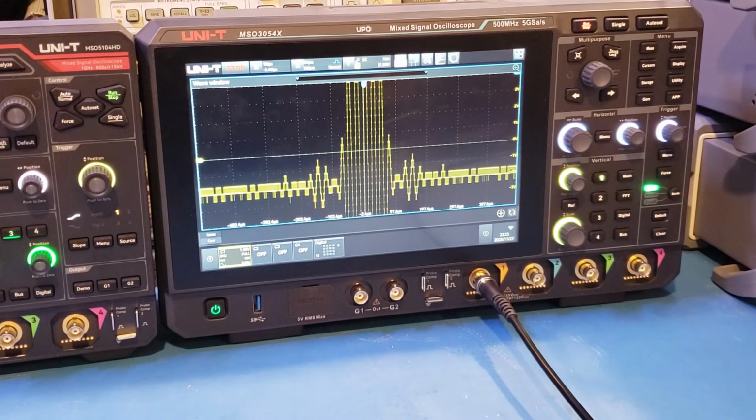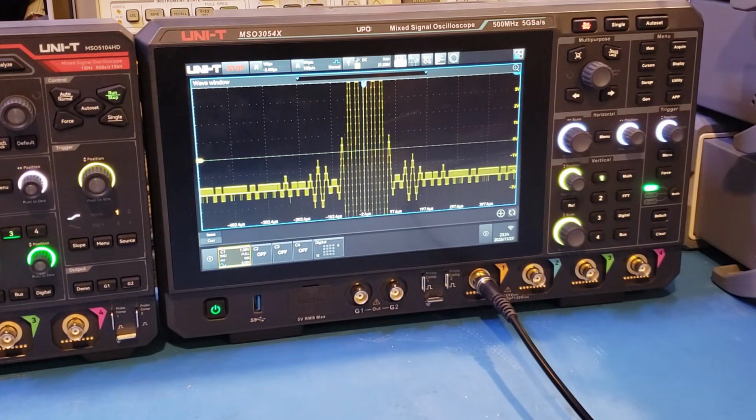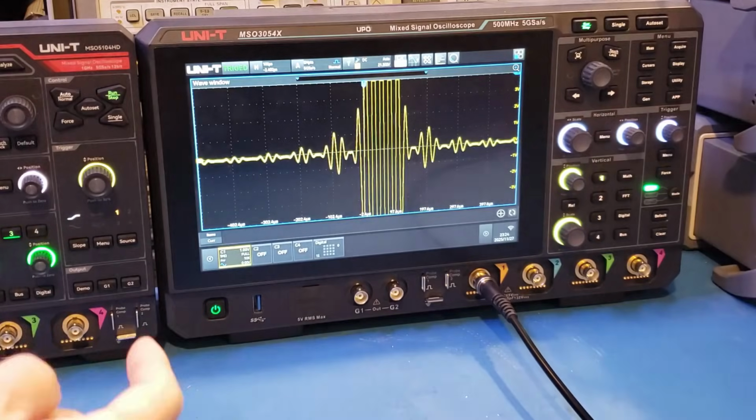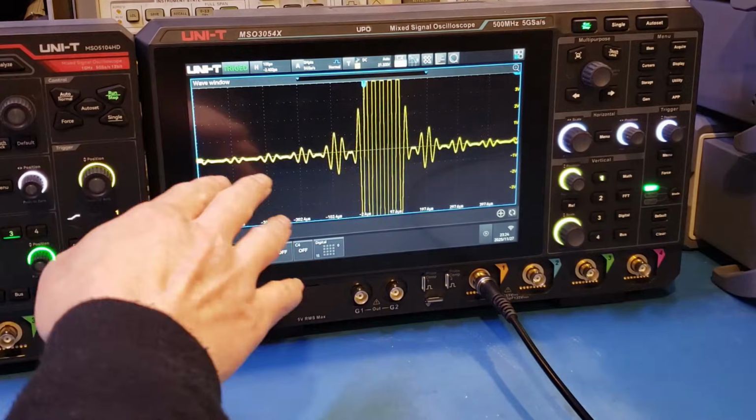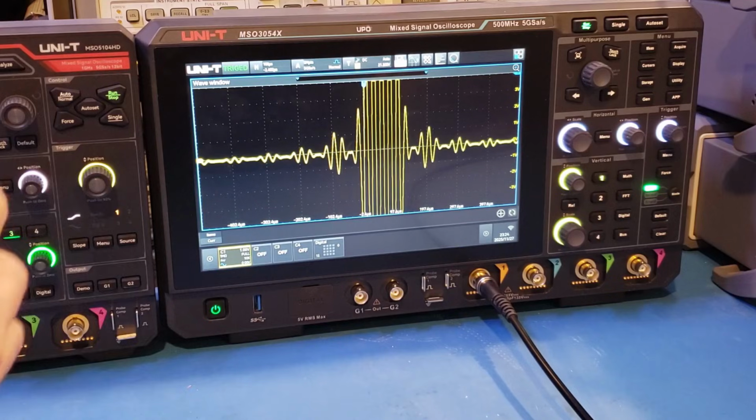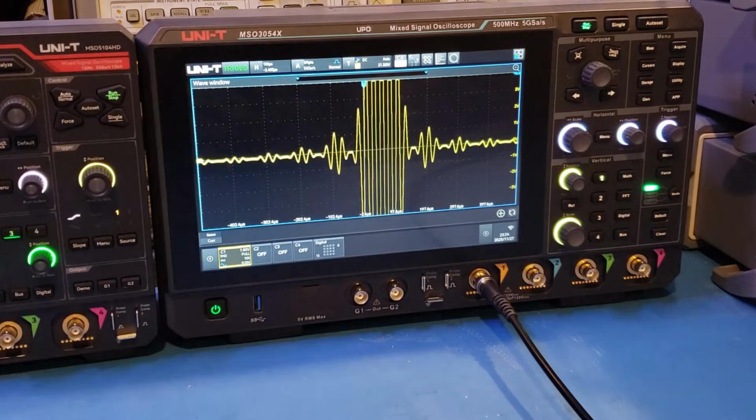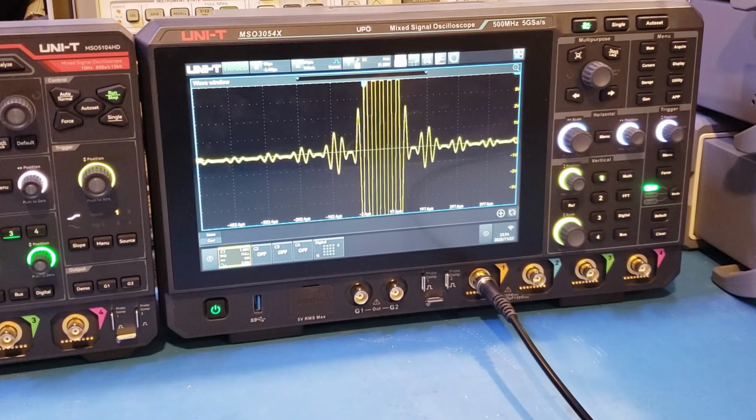Of course, for repetitive signals, you could just recapture the signal again with different vertical settings, so the captured signal magnitude can be higher, and therefore you will have more bits representing the signal, and the resolution will be naturally higher. For example, right now if I resume acquisition, you can see that at the same scale, of course, we can see a lot more detail. That's because right now we're digitizing this section of the signal with all 8 bits. So for this reason, in most cases, you can actually get by with an 8-bit scope, but you will need to set a vertical amplification such that the signal of interest takes up as much of the amplitude as possible for the best resolution. And sometimes you may need to take multiple measurements to achieve that.